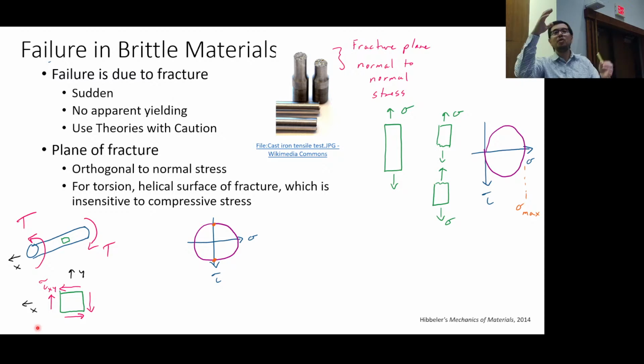Right, because on a Mohr circle, you move around the circle, right? So where am I? Max shear stress. Yes. Okay, so I'm here, or the top. Yes, so I've got essentially a line going across. But I'd be down here, right? Because that's where I have my tau max, and that's where I have zero normal stress. Okay, so I'm there.